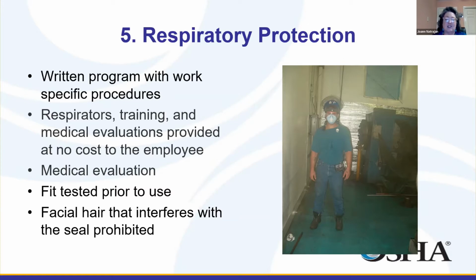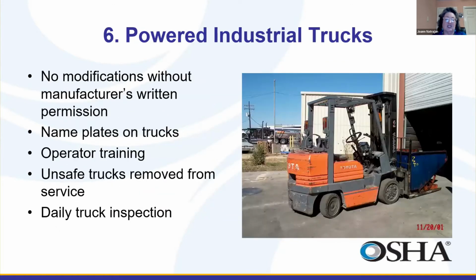And it's not just, things smell a little and we're going to give everybody a mask to deal with it. Well, you might be able to get away with, there's a provision for filtering facepiece masks, essentially dust masks, under certain conditions where you don't have to do very much according to the OSHA regulation. But most of the time, if it's anything other than voluntary use and you are over a permissible exposure limit, you will have to do a number of things for that regulation. So it's a lot of stuff.